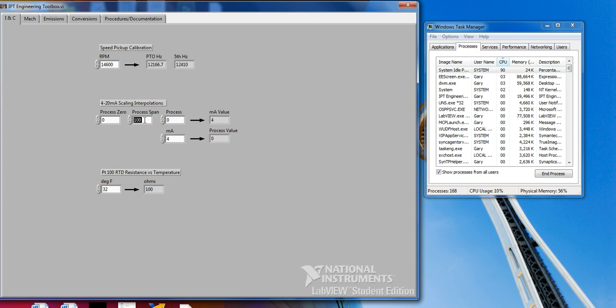If you want to determine certain milliamps, or what milliamps should happen in a certain process, you would need to know the range that the instrument's set calibrated for in the first place. But let's say 0 to 400 degrees, and we wanted to know how many milliamps 100 degrees is, and you would know that it should be 8 milliamps.